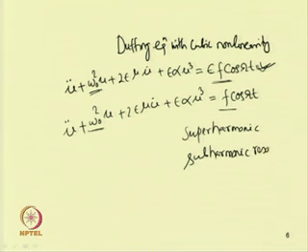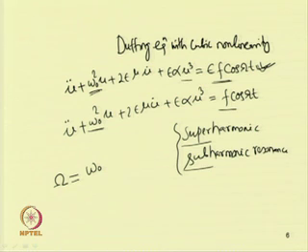So, in case of cubic nonlinearity, we have already studied the primary resonance condition, in which omega, the external frequency, is nearly equal to the natural frequency or the linear frequency of the system. In case of the subharmonic and superharmonic resonances, depending on the nonlinearity, that means in this case cubic nonlinearity, we have the resonance conditions like this.